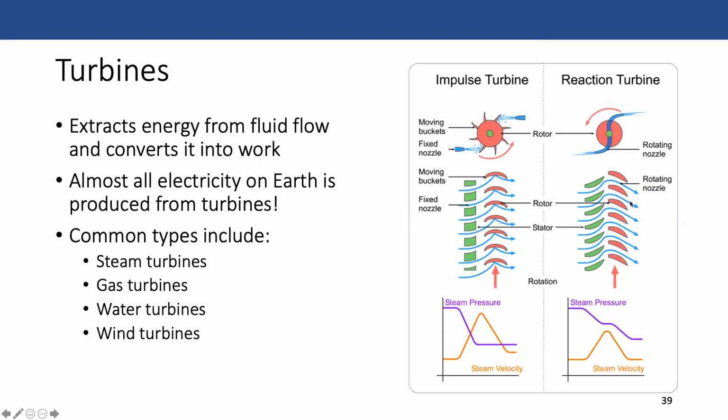In our reaction turbine, it's a similar type of process. You've got these fixed nozzles, these are the stators, and then the red portion, which is the rotors, which are moving. And so the gas gets pushed in this direction. It goes and then it rotates the rotors and then moves outwards like this. Okay, so high level, you're basically getting air to move through the turbine quickly.